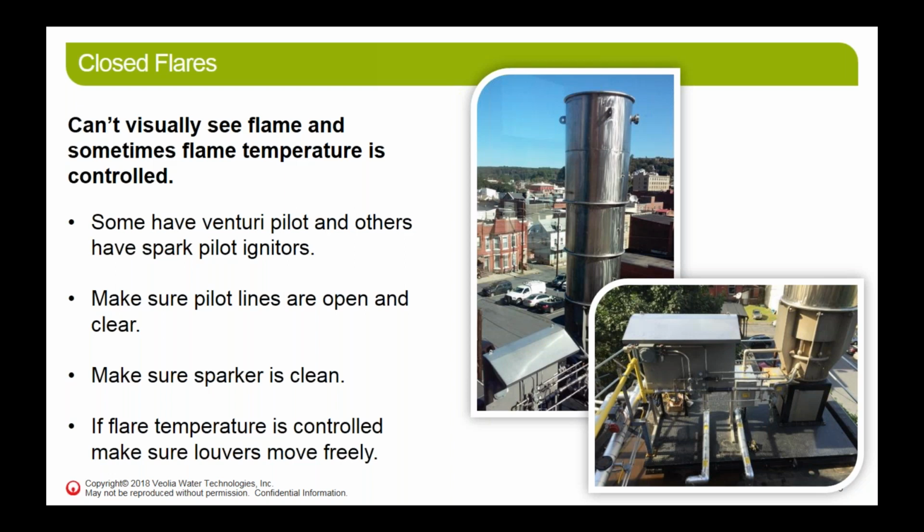And enclosed flares are also used in facilities where you have a gas discharge regulation. Like you can only burn so many pounds of sulfur a day, and you have to burn your gas at a given temperature.